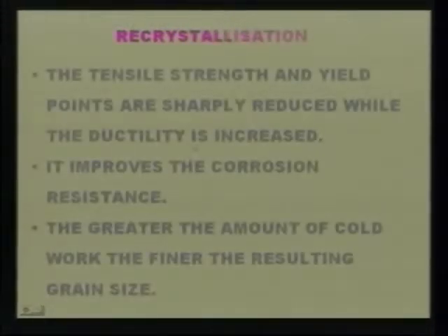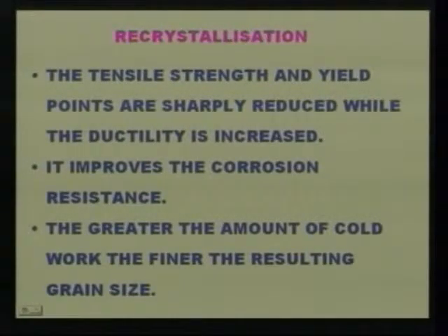Now, let us see some important points on recrystallization. Due to recrystallization, the tensile strength and yield points are sharply reduced while the ductility is increased. The next point is that it improves the corrosion resistance. And the greater the amount of cold work, the finer the resulting grain size. This is usually followed by grain growth, during which the larger recrystallized grains grow at the expense of the smaller ones. Soluble impurities raise the recrystallization temperature.